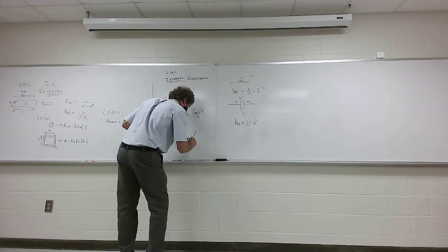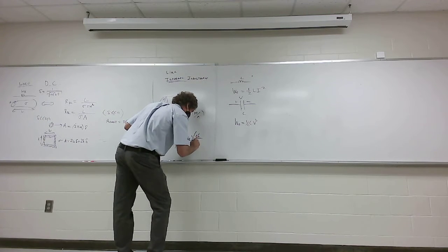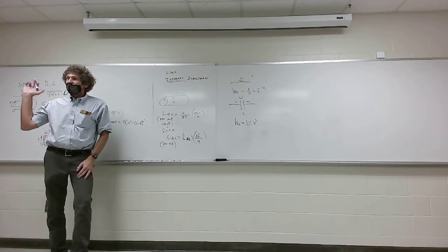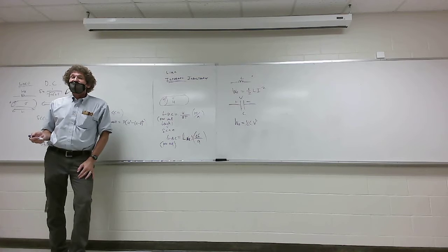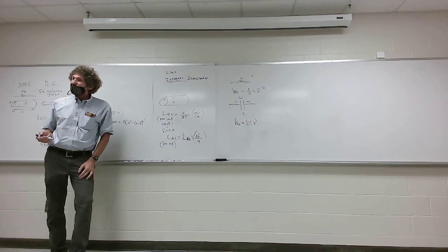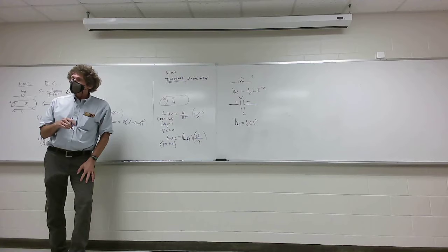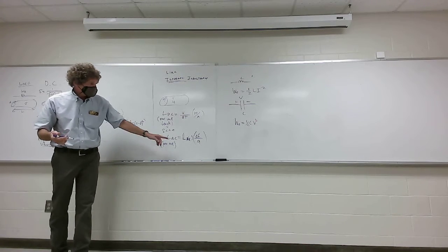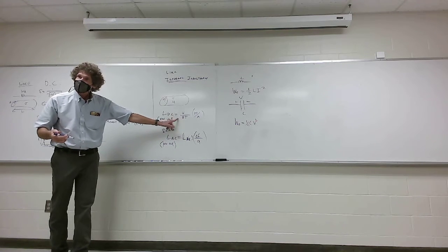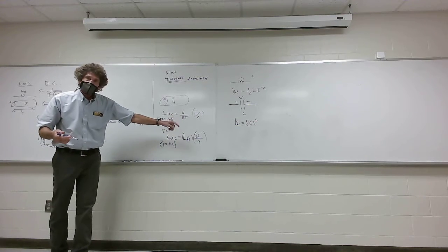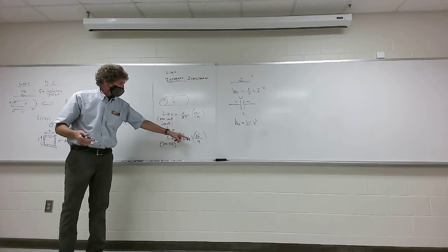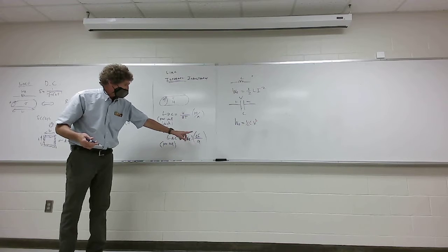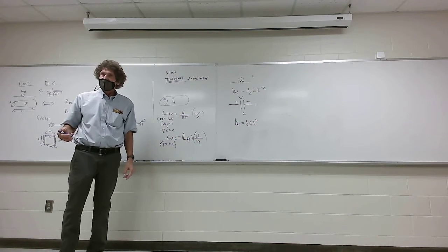And then you simply put 2 skin depth over the radius A. Now, anybody looked that up in his book? No? It's there. I gave you the equation last time. Look it up. I know you had a quiz, but just look it up. It's different than the one I showed you. I like just putting L DC because that's right there, times that. Wentworth does it. He puts this here, and then he gets rid of the 2. So it's mu over 4 pi A, and the skin depth's on top. Y'all follow me? That's what's in his book.